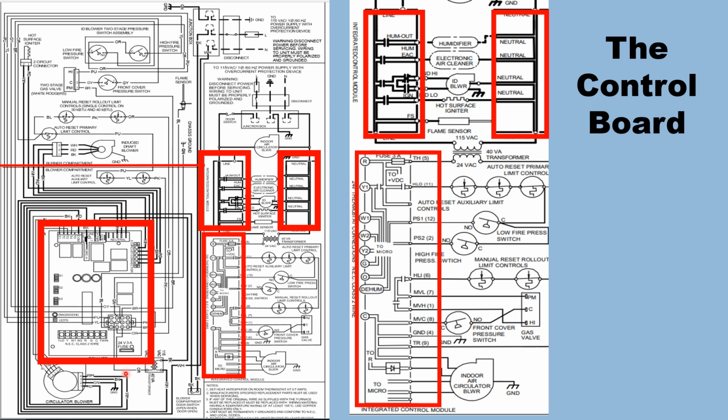And if we were to look at the board here in the pictorial, here's the board in the ladder, these 3 points. So we look at that, and again, all of these are in series circuits, and these are series parallel circuits. They're wired in parallel for the power, so that each one gets equal voltage, but maybe the amp draws are different, so you'd have different amperage readings. But they get all the same voltage here. That's why it's called parallel.